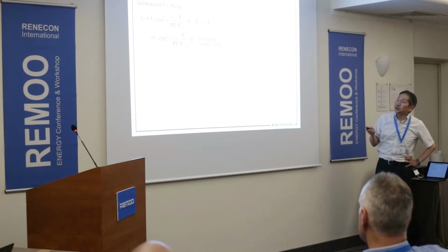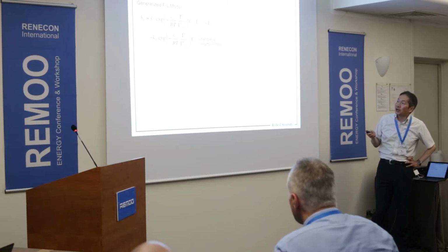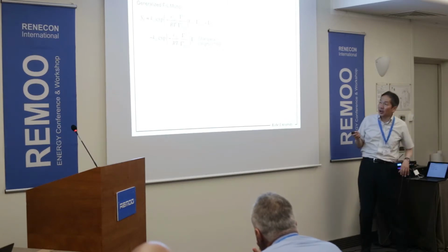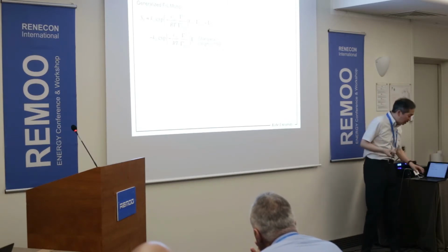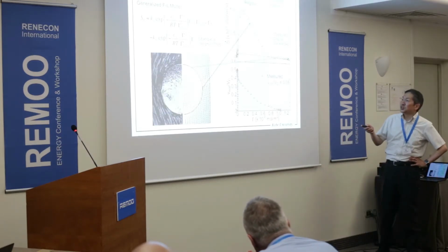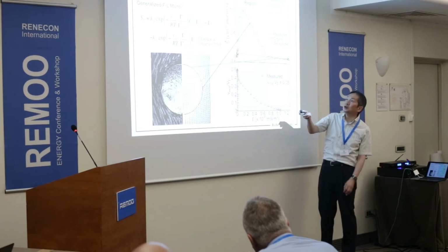As I mentioned, usually we use this original Langmuir-Levich model for the adsorption-desorption kinetics, but recently some people have proposed this generalized Langmuir-Levich model, which is used for very special cases. If we compare our measured flux with the data in the tail region, the stagnant region, this line is by the Langmuir-Levich model, so in the stagnant interface this model does good work.